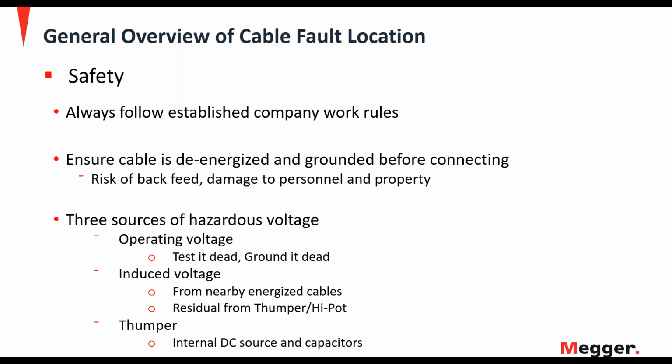And then your third source of possible energy is the thumper itself. It is a high voltage device. It has a high voltage DC power supply in it, and one or more capacitors that could hold energy inside of them. So these are the three sources of voltage that you always need to be aware of when you're working with a thumper out in the field.